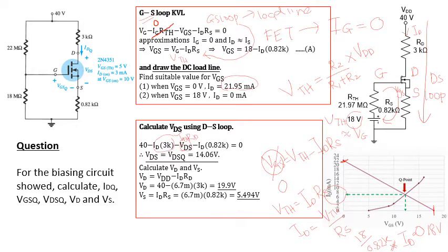And then minus the VDS because of the current flowing through this channel. So you have to minus the VDS. Minus the ID, this one because of the series. So we assume the current that flows across this resistor is the ID, because ID is IS, the same. So this equals 0.